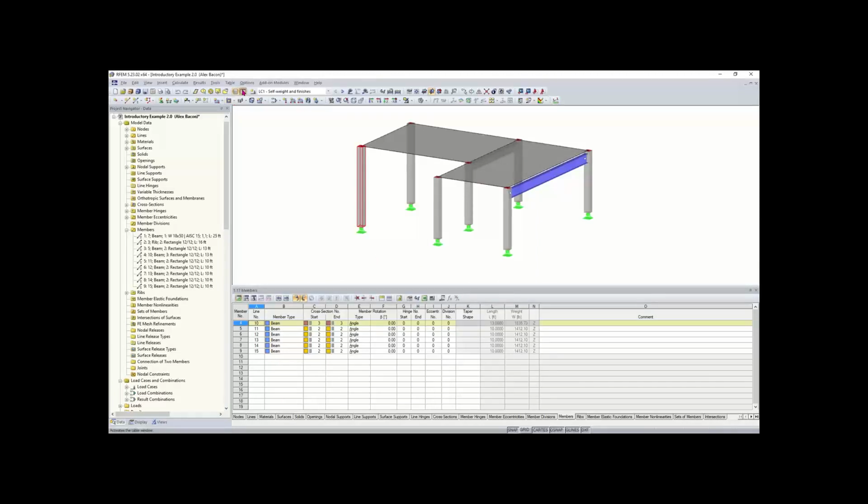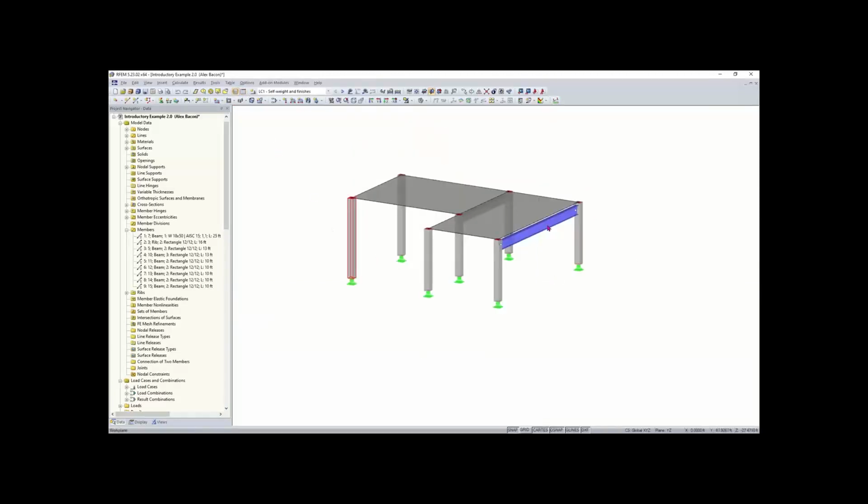After that, another thing to go over is this is called the work window here. Within here you can draw lines, surfaces, etc. We'll be going over all of the finer details with that. Then up here you have your toolbar, and this includes all of your tools and everything, which are organized within different subcategories. If your toolbar looks a little messy and you just want to clean it up, you can right-click anywhere within this gray space, go down here to reset the default, and then click yes, and then your toolbar will look like mine if you're having trouble finding the tools.